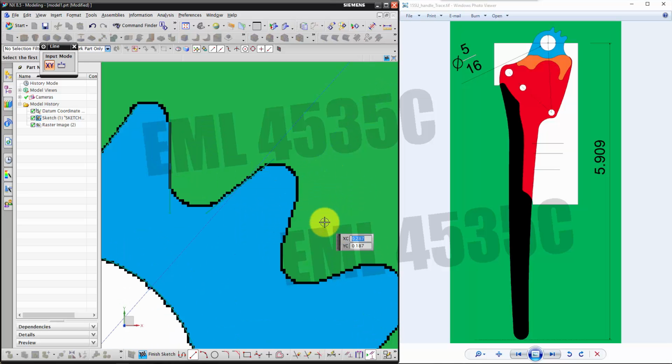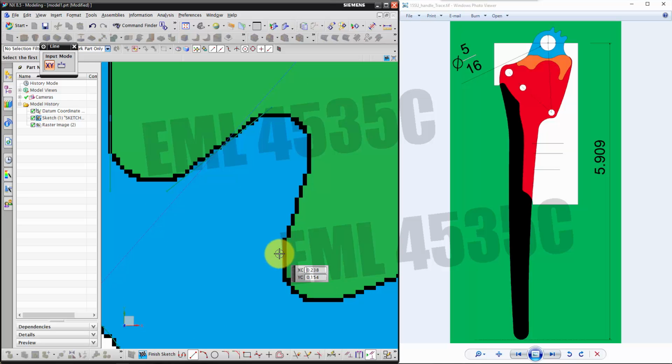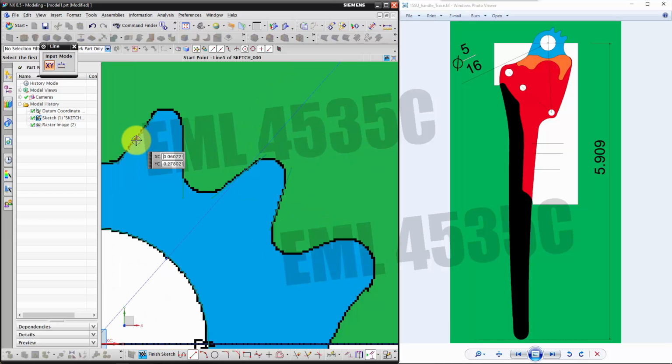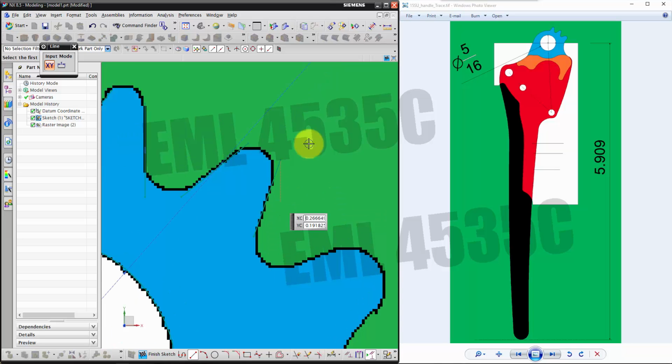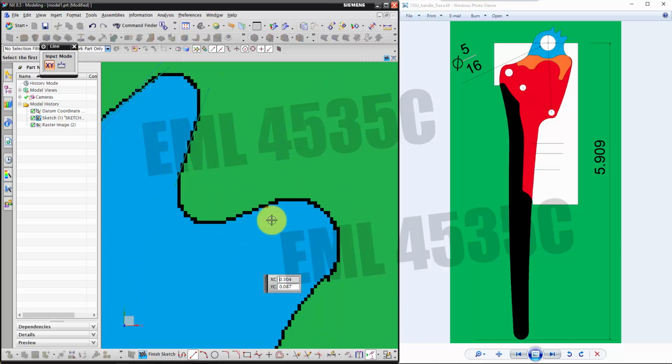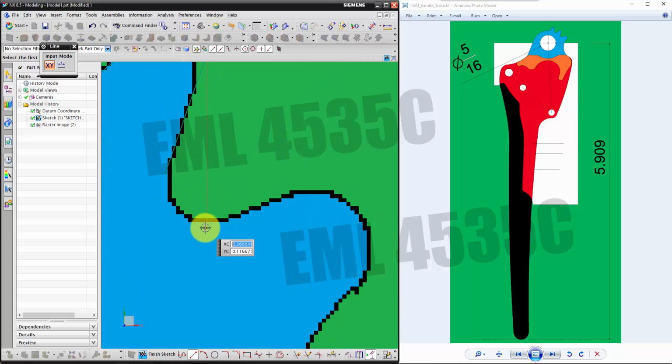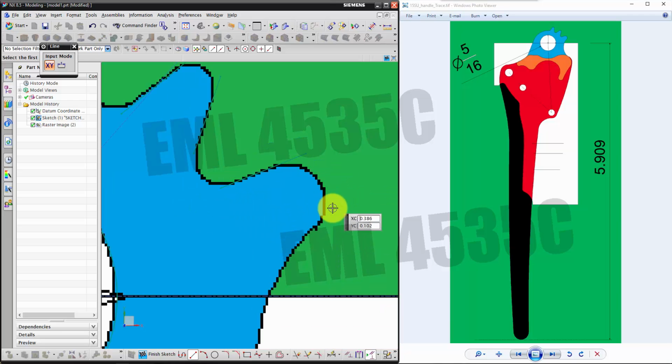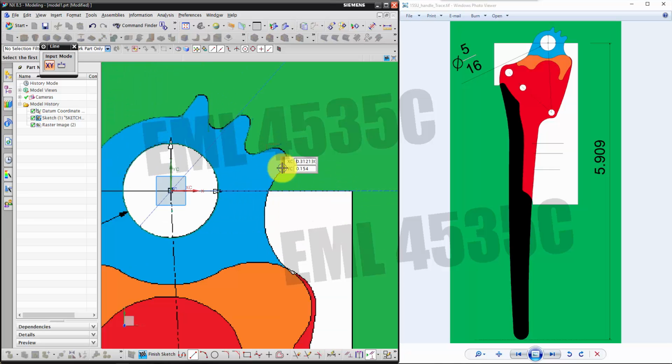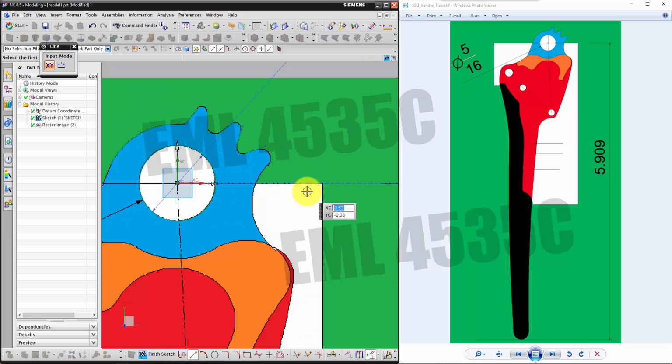And the trick, or the experience I found when I was doing this tracing, is always skip one section. Just do one and skip one, and draw another one, skip another one. So this way, when you connect them, you can use a fillet. This one will be tangent on both, or a 3-point arc. You can control the intervals of the lines you just drew, and you don't have to worry about how to connect these things.